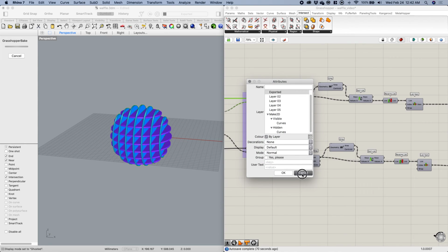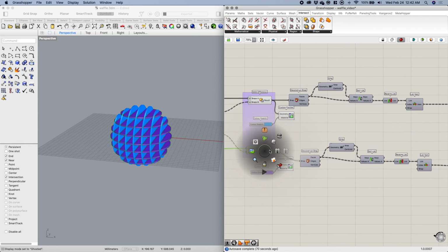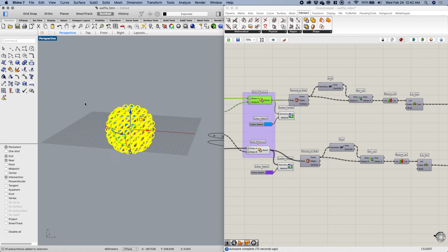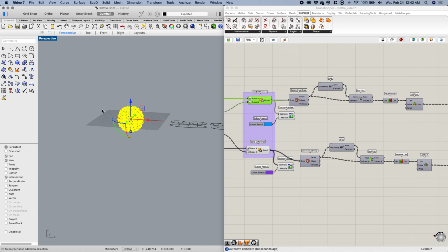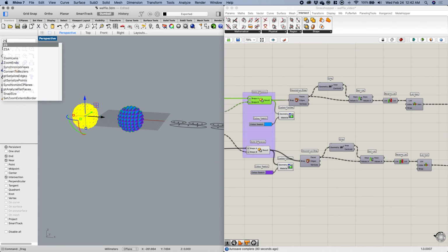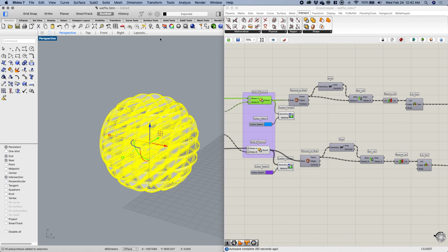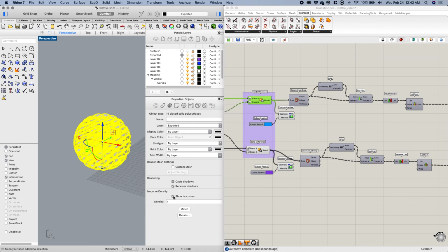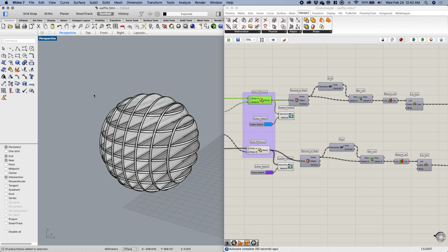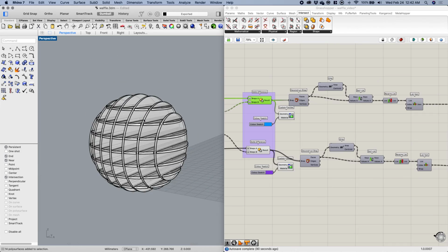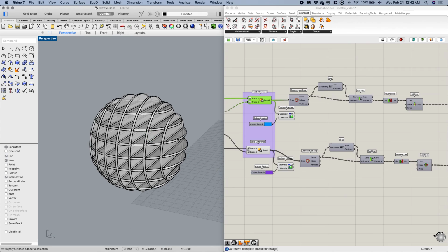Let's see here. Bake each set of objects out right here. So we have 14 poly surfaces now. If I type ZS, okay. So I have these objects, and I'm going to turn off isocurves. So I kind of see just like a cleaner rendered ghosted view.